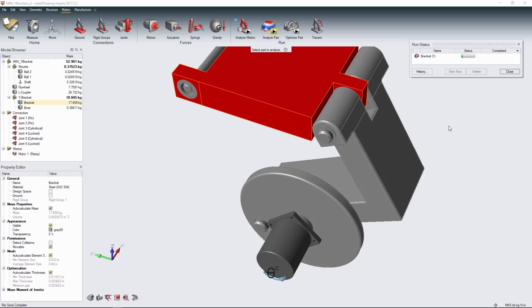Now, I am doing these studies in real time right now. Once we get to the shape optimization, I might run one study in real time, but I have several studies done up, so I want to show you the different results. Because once we start running the shape optimization, this is where we add symmetry planes, we add manufacturing constraints, and we can toy around with those to achieve different results. So it's normal to run multiple iterations of the shape optimization.